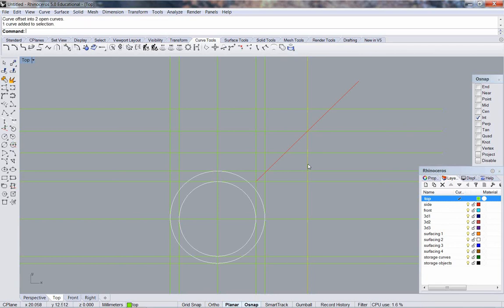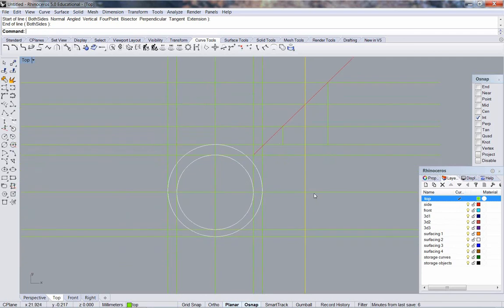Going to apply drafting technique now. In Rhino drawing, I already know it's 10 millimeters and I would just repeat the command. But I want to still emphasize traditional drafting technique to some degree. So we are going to take a construction line from where this width reaches the miter curve. We're going to pull straight down, holding down the shift key, until it intersects with the top line of the ring. Same thing with the back. That is our topmost